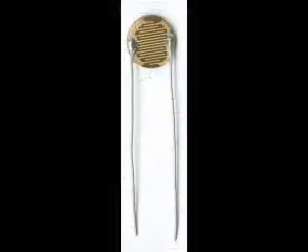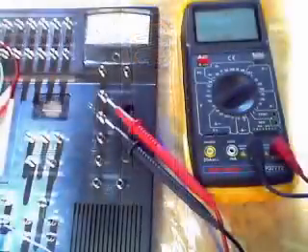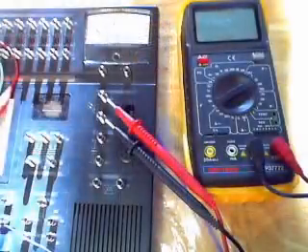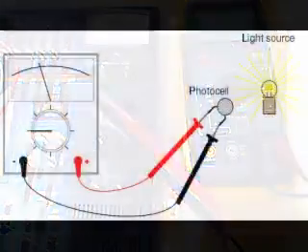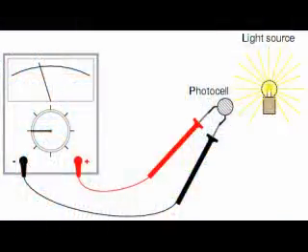A photoresistor or photocell is a resistor that changes resistance depending upon the amount of light hitting it. They are sometimes called light-dependent resistors, LDRs. The Electronics Learning Lab has a photoresistor in the upper right-hand corner. Connect your meter to the terminals of a photocell and measure the change in resistance created by differences in the light exposure. You may want to use alligator clip jumper wires to make the connections with the component, leaving your hands free to hold the photocell to a light source and change the meter ranges. What happens when the light hitting the photoresistor gets brighter? Darker?